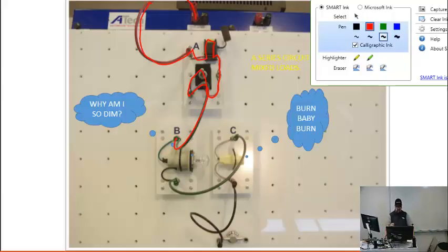Well, let's look. Now, this bulb is not lit up. Could it be a bad bulb? We'll talk a little bit about why it could or could not be. But this bulb is lit up, right? This bulb is nice and bright. That tells me it's getting voltage and it's getting ground. So it's getting ground right here, so it's got ground coming up to it. So really the only way for it to get voltage is to go through this bulb. Right? So we went through this bulb, we went out.